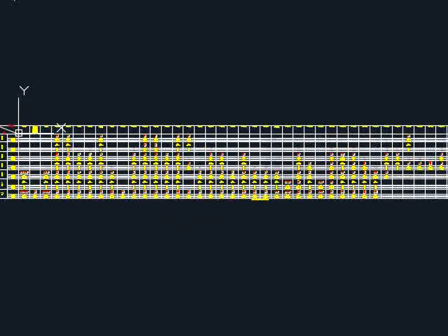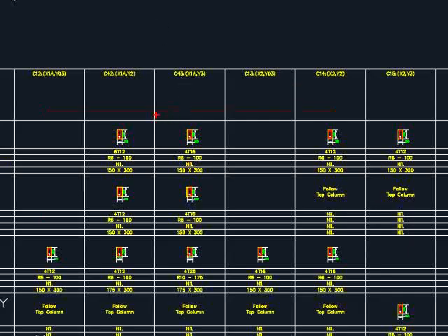And also we see the software generates a full list of the columns. Every single column has a different design, and each design here is applicable for one type of reinforcement bar. This is very hard for the site personnel to manage. That means there will be post-processing for you to group the columns together so that you have a limited number of column designs to be applied throughout the structure. The same principle applies to the foundations. Normally we will prefer certain standardized sizes for easy management in terms of the construction process.